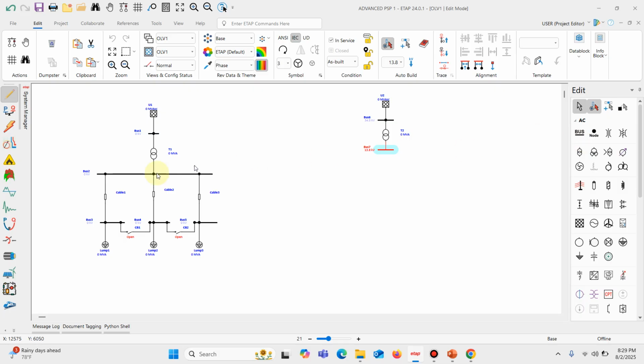Now, assuming we want similar scenarios, this is where it gets tricky. Yes, you still have to get your hands dirty because the auto build will not automatically expand your bus bar for you. So you come by yourself and you expand your bus bar. So we need cables. We can also double click and drop your cables. In the auto build, you do not have the feature of double clicking, so you turn off the auto build for this double clicking feature, where you can drop as many as you wish, and then we can connect this to the bus bar.